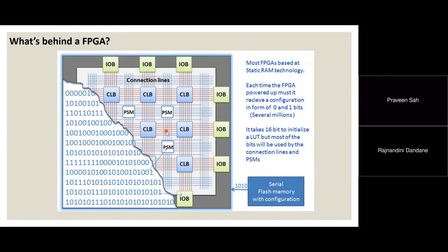And how do you configure these FPGAs? Using flash memory, whatever compatible flash memory there is, whether you are using Xilinx, Altera, or Lattice. There are different flash memories, quad SPI, octal. You can choose based on the design guidelines by the vendors. Don't select anything haphazardly.